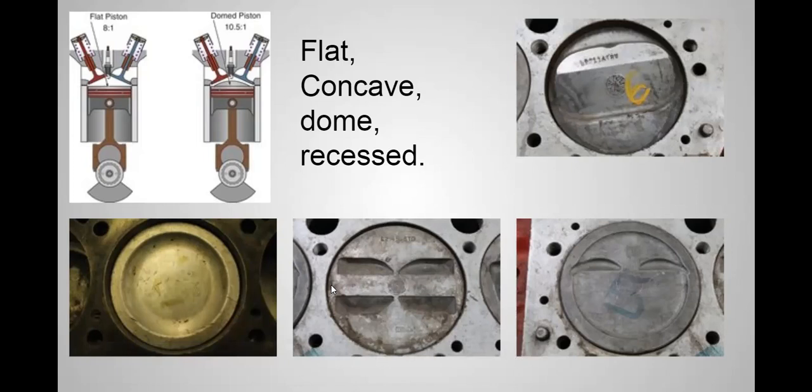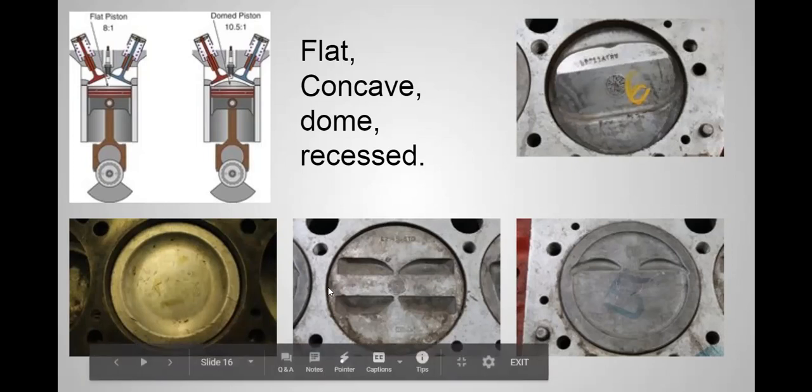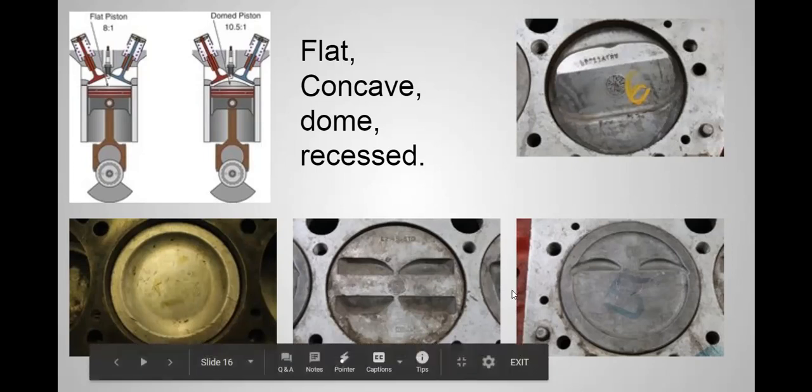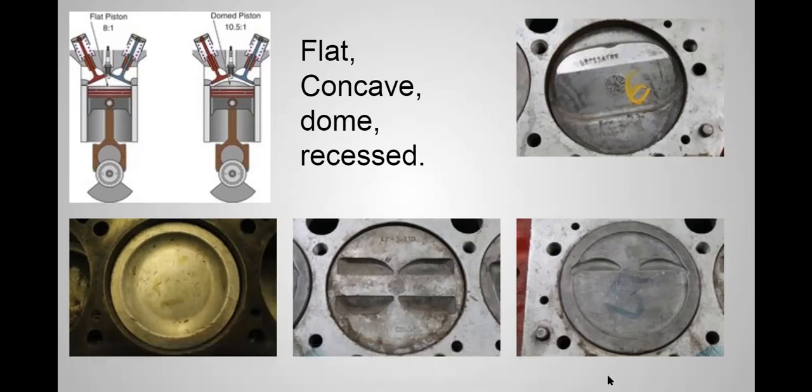The front of the engine would be, for most cars, the side of the engine where the belts and the fan are located. By pointing that to the front of the engine, that's going to give us the offset part of the piston on the correct side of the engine. This way we can control that major thrust and that minor thrust.